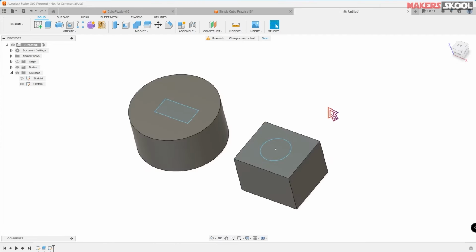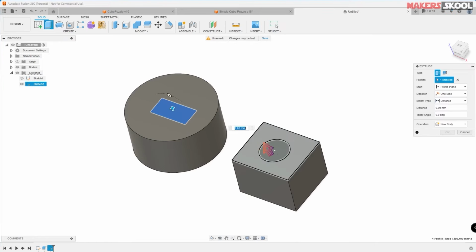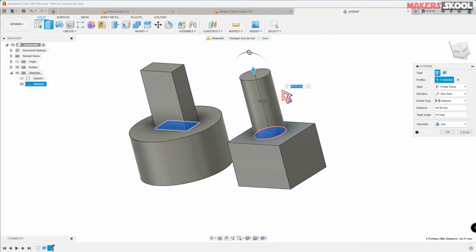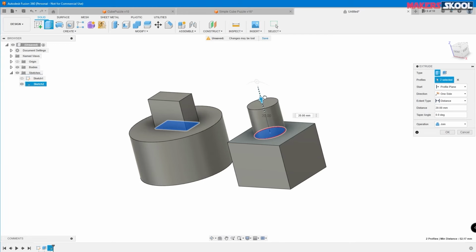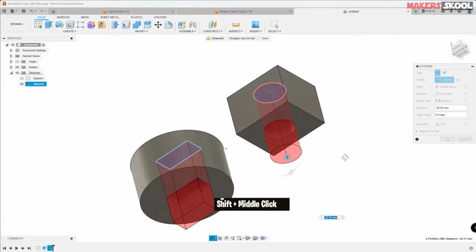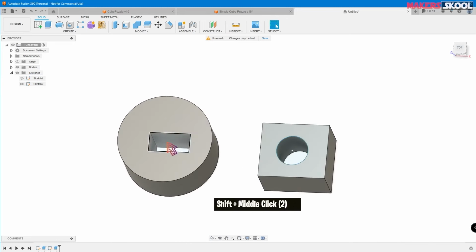As discussed earlier, the extrude function can be used to create a solid component when you extrude, but it is also used to remove or cut a component. If you drag the sketch down below the solid component, you can see that the component has been cut out, it has been removed from the solid part.